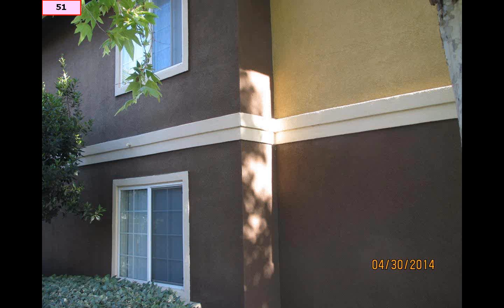So the summary slide here. From my perspective, a forensic perspective, what this tells me is that moisture as water vapor is always entering these exterior walls from the interior during heated periods, from the exterior during the heated periods, and also from the interior when these periods of massive moisture generation occur.